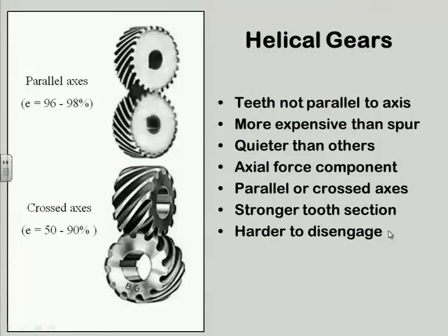Biggest disadvantage here is the axial thrust. If I'm passing 10,000 horsepower to a propeller of a destroyer, and I'm using helical gears because I don't want the enemy to hear me coming, which is a pretty good idea, I'm going to have one big axial thrust bearing in there that's going to be lossy.